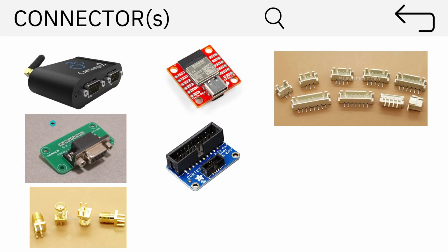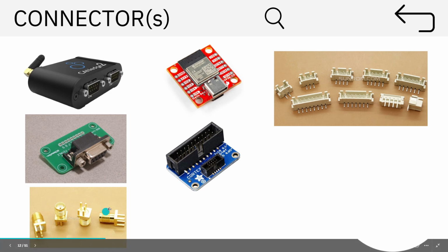Let's see the connector. If you see, I took this reference from one of the famous CAN logger devices, which is very common. We have this as a DB9 connector, and you will see this sort of connector being available. So we are going to use this. You can have an OBD connector option also, but we are not using it. In terms of interfaces, we can have a Type-C interface where we can directly flash something over here, and same goes for the GSM part. Then you have an SMA connector for the external antennas.